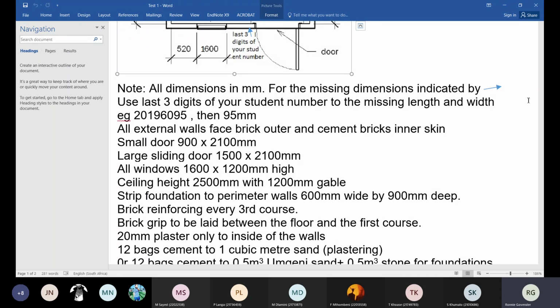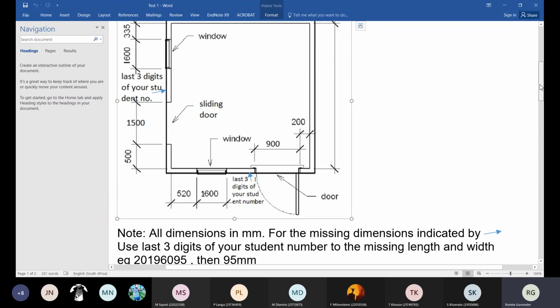So if you just took the total area of your brickwork, in other words, excluding all the openings, you can't take the openings now. You take away the openings and you multiply that by 0.02. That would have given you the volume of your plaster that's required, right? So that was fairly straightforward. As I said, there was nothing tricky for you.